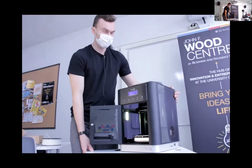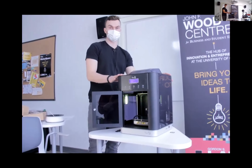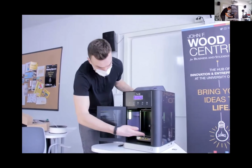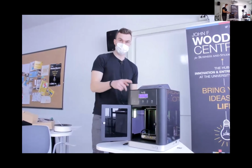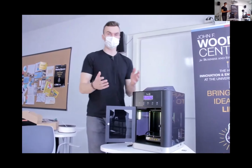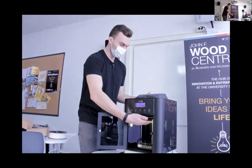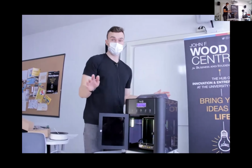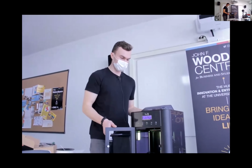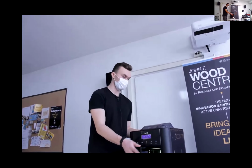Okay, so let's recap what we've done so far. So on the Cubicon, we turned it on. We cleaned off the auto leveling contacts. We preheated it. We unloaded our old roll of filament. We unboxed and put on a new roll of filament, and we loaded it successfully. We saw it extrude, so we know we're good there. So that's good. And we're kind of ready to print now because we're preheated and we have our filament loaded.